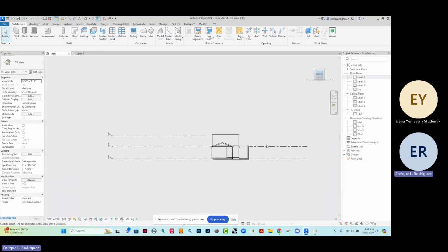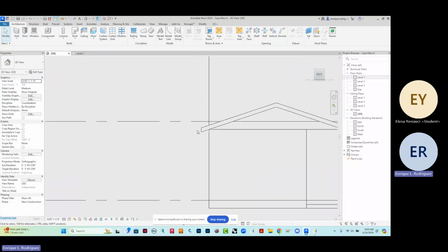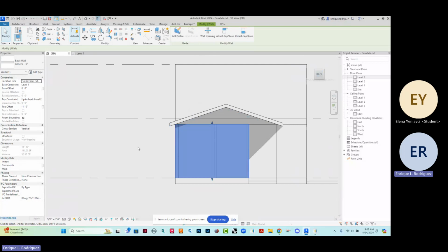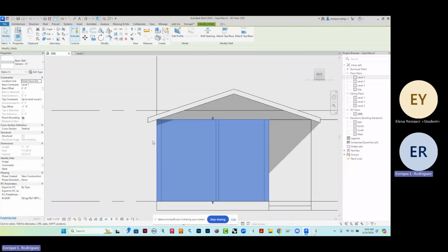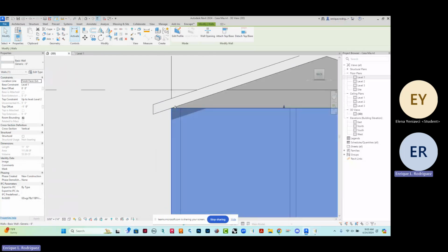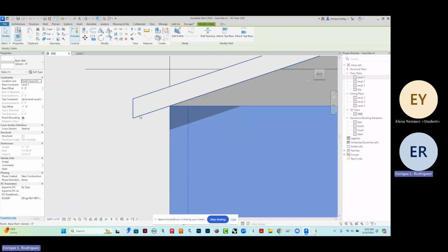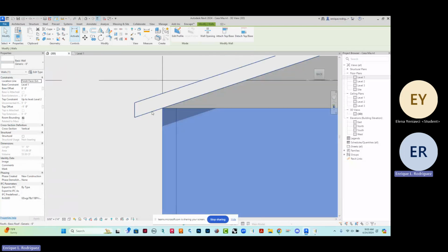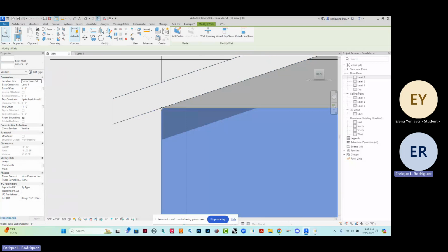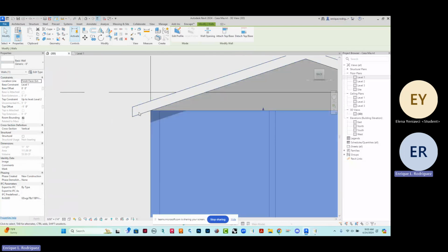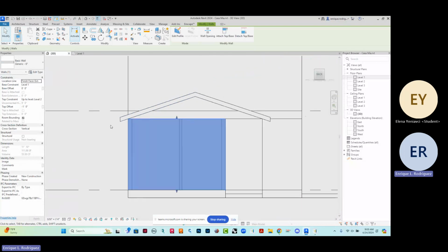Now I'm going to go to the back view in here so you can see what ended up happening. This is my front wall for that lower roof. Because I picked walls here on both sides, the bearing point of the roof is right at the 9 feet, which is what was listed there, and it matches the top of the wall. Now, structurally and in construction, you wouldn't do that anyways because it creates too much of a pressure point on that wood right at that point. But you notice that the roof continues down beyond that point.